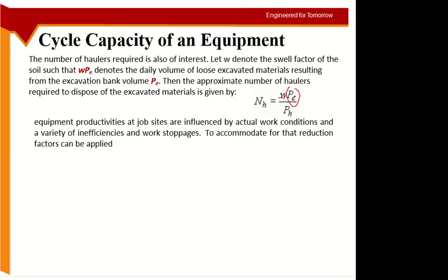So remember, material excavated in 1 day, multiplied by the swell factor, gives the actual quantity to be hauled in 1 day. Divide by the productivity of the hauler for 1 day, and you get the number of haulers required for each day.